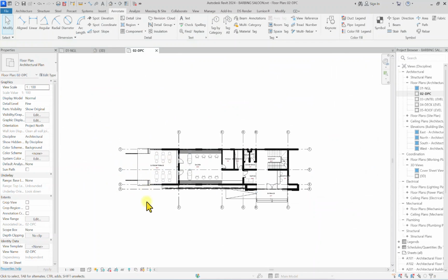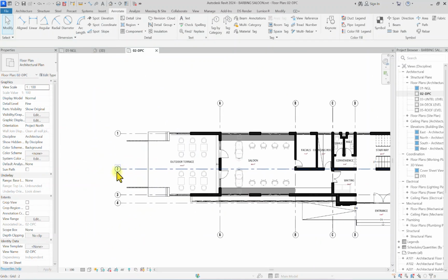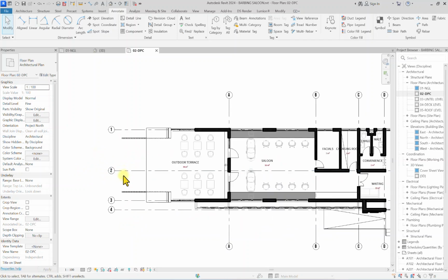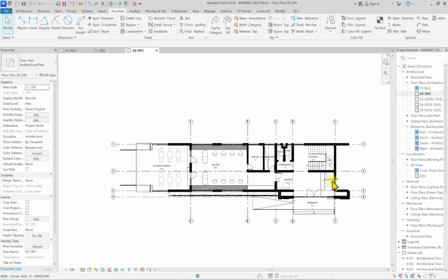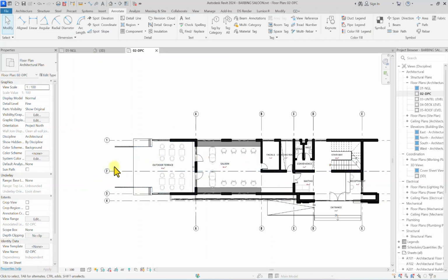So now we're going to use what they call color schemes. So color schemes are tools in Revit that demarcate rooms into different colors. So it will visually allow people viewing the floor plans to easily visualize and say, okay, this space, this color represents this space and this space. So it's just a graphic stuff for enhancing presentation.